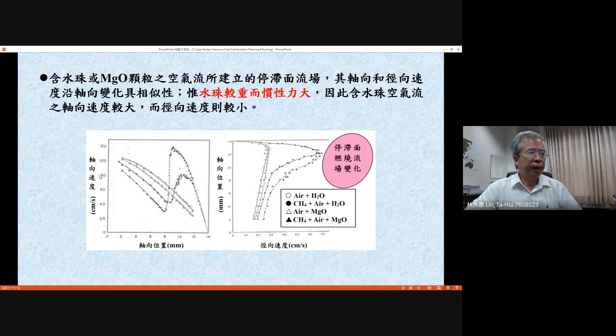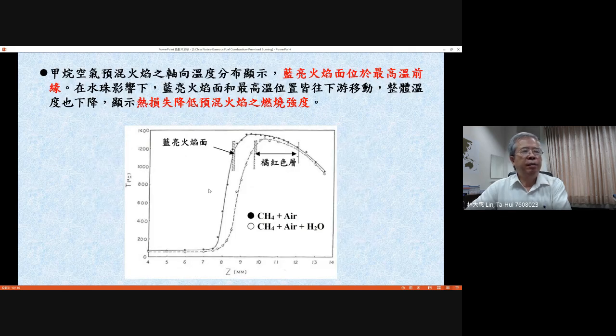Okay. In this sense, you can figure out what the flame speed is for this premixed flame. Actually, you realize the determination of your flame speed can be identified at the point of the temperature increase, right? Because there is a region where the temperature remains constant.